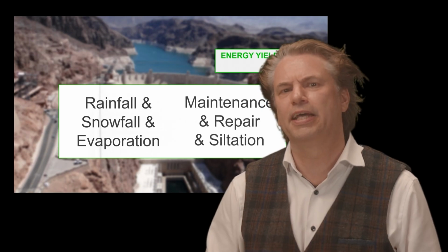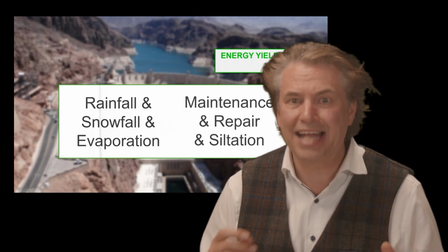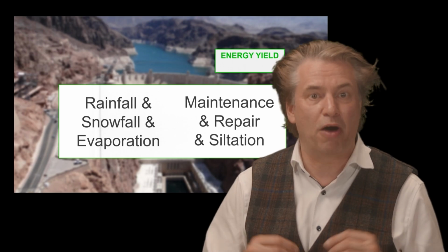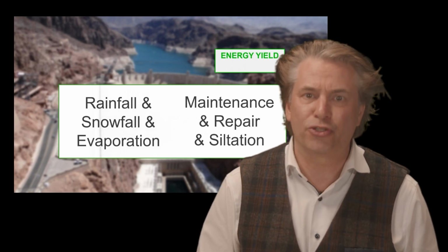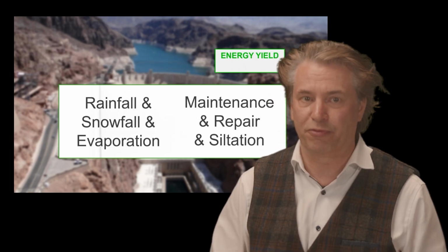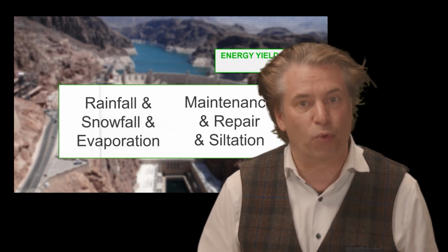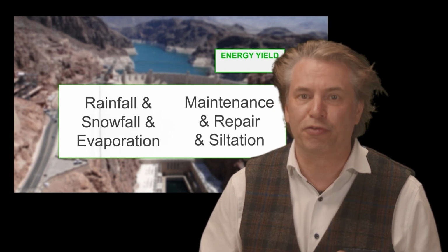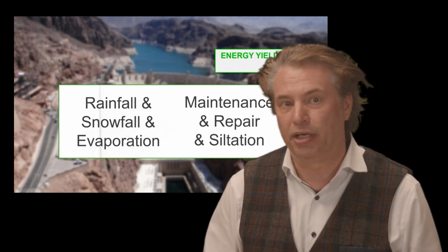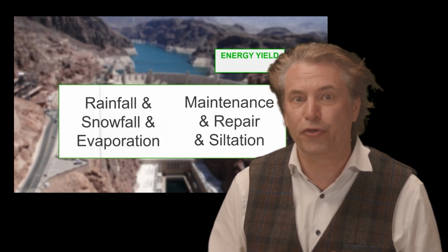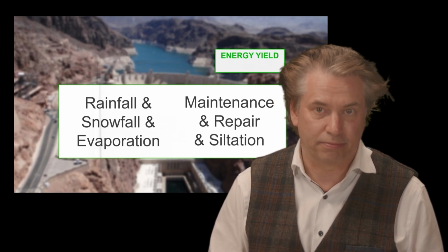Another factor that can impact the energy yield and capacity factor is that the power plant, like many systems, has a certain downtime for maintenance and repair. Furthermore, the storage capacity of the top water reservoir can be reduced over time due to sediment accumulation, referred to as siltation.